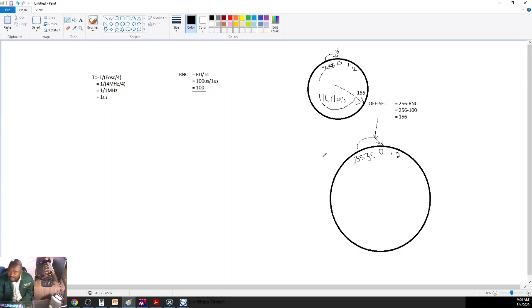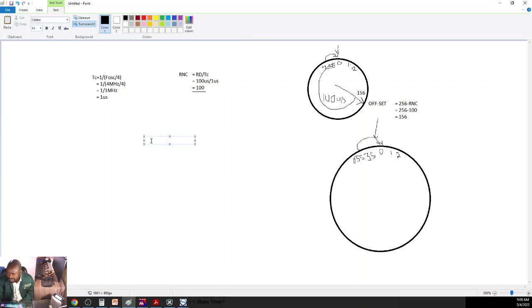Now, the calculations I said, they will remain the same because if we use internal clock, this would still be the running speed if we use a prescaler of 1:1. But now, our required delay has changed. Required number of counts will be equal to the required delay divided by the current time per count.